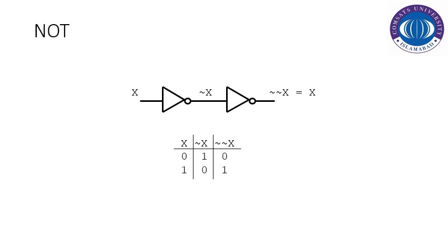Here x has been inverted, then double inverted to give x, so they cancel each other's effect. This is the same as a wire. If I don't use a NOT gate, it's sufficient. As far as cost analysis is concerned, the first approach is costly, since I have to pay for two NOT gates, while the second one is just a wire. I don't have to pay anything extra.